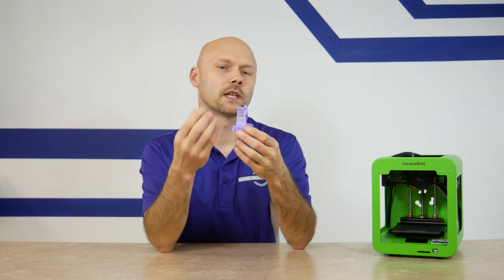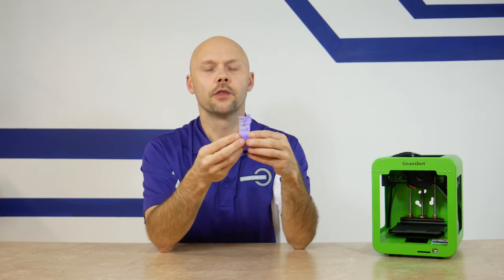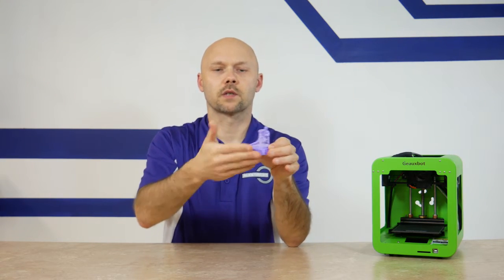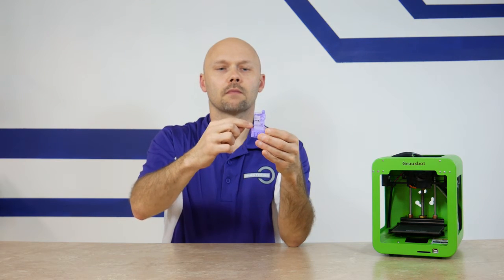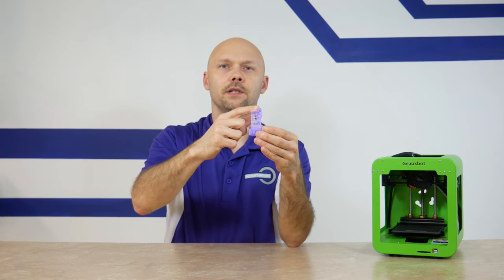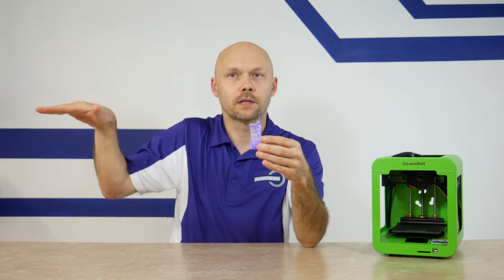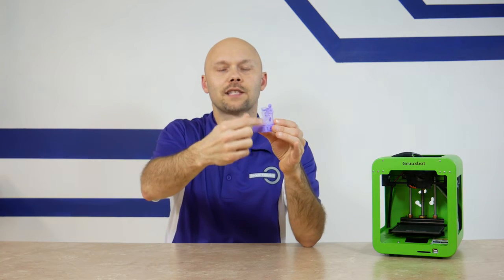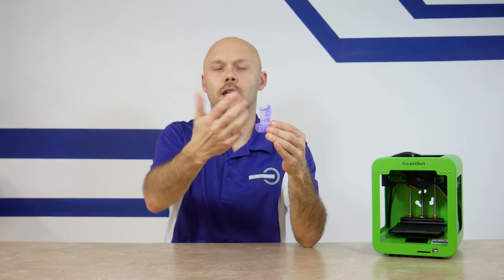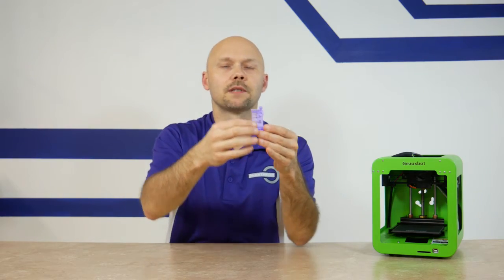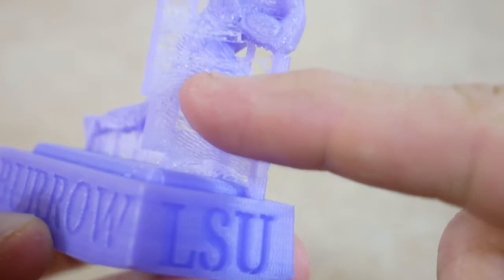But to explain to you a little bit more about support material, 3D printing starts from the bottom and works its way up. And as it goes up, the layers continue to build on top of each other. If you have an object like this with an arm extended out, the plastic would actually fall to the ground and never even make it, and it would just be a jumbled mess. So what happens is the 3D printer puts these tiny structures that break off, just like this.